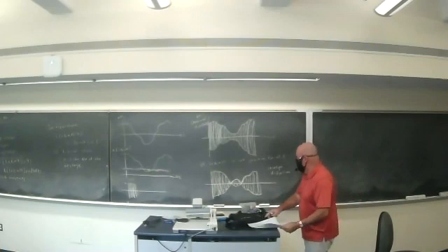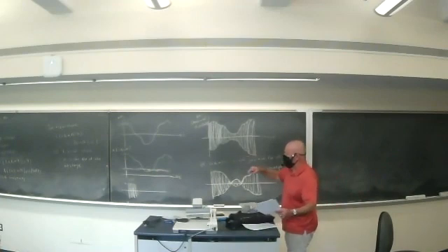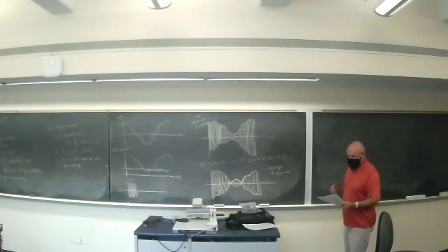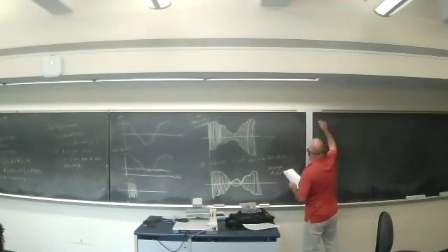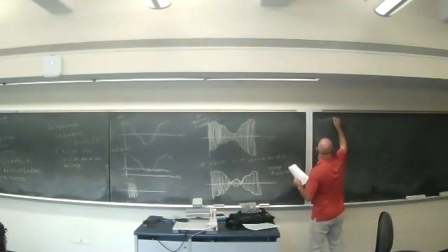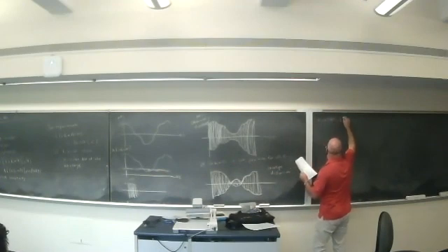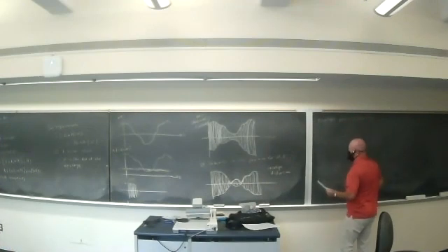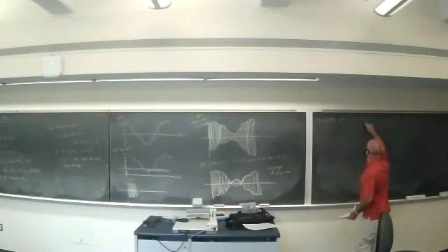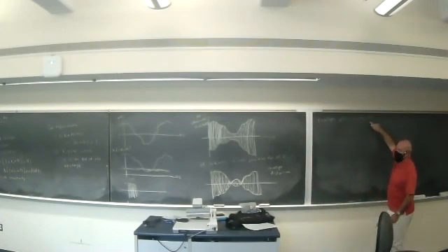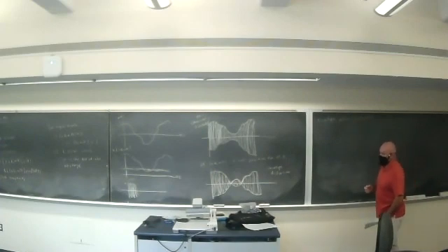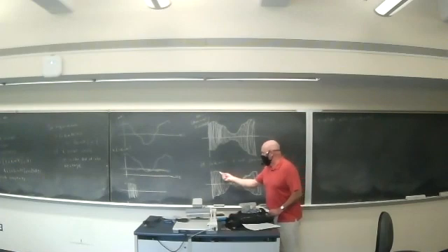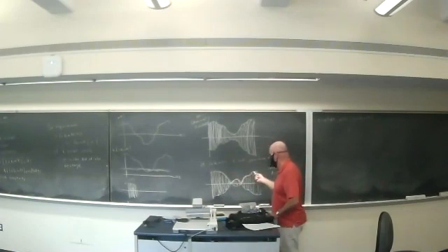Okay. So this requirement here, that first requirement, the envelope e(t) is equal to the absolute value of 1 plus Ka m(t). Okay. And this condition that this is always greater than 0, if that's always positive, we can do away with the absolute value signs, right? The envelope would always be this. Okay.